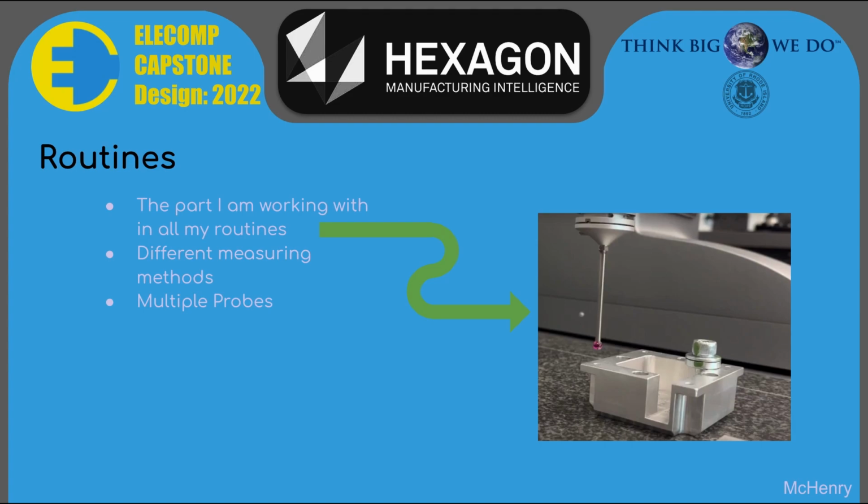And with these routines that we developed in PCDMIS, I've also contributed to setting up a probe rack in PCDMIS and making other qualification routines. With these routines, we can gather more data about what's going on with the probe.